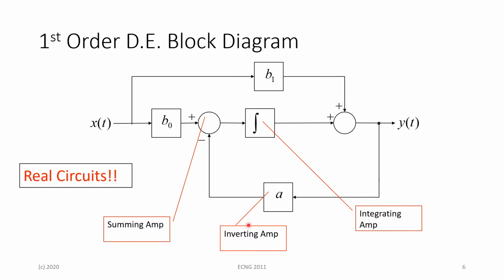And all of these components here are basically real circuits. So you can use a block diagram to map out your real circuits in a simplified form. Instead of having to draw a physical op amp here, another physical op amp here, and then draw the connections using the resistor symbols, you can represent this using a block diagram instead.